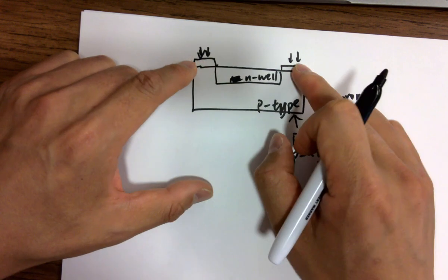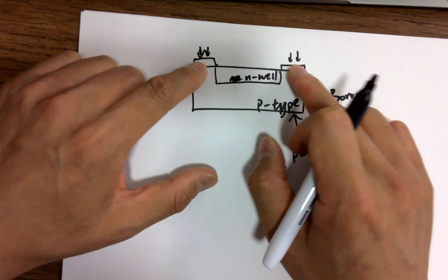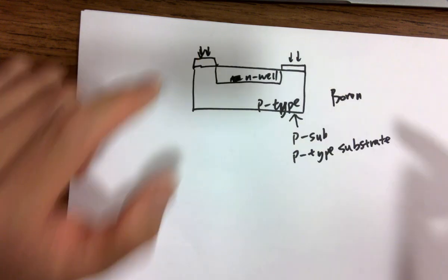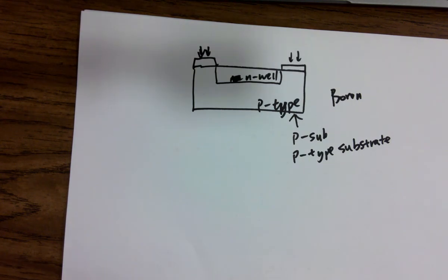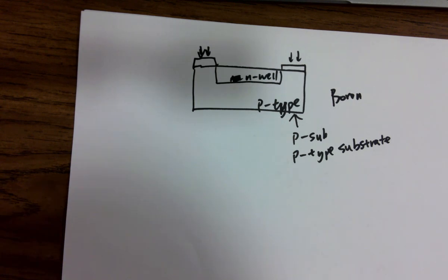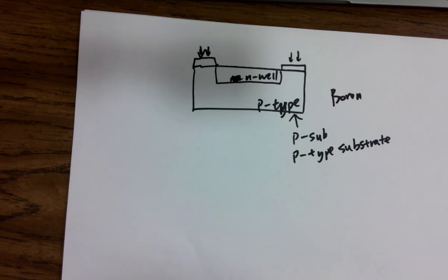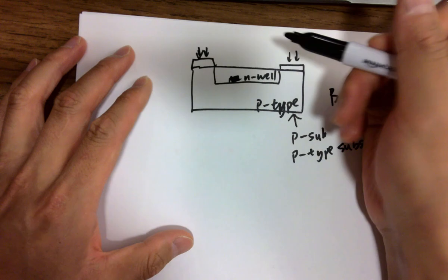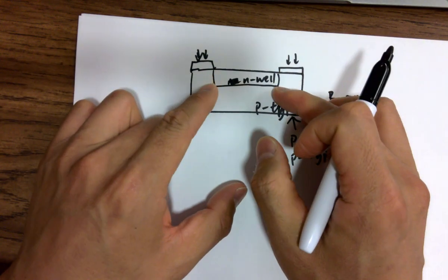That's how that works. And we can use a lot of technologies to block it. It's called photolithography, including the photoresists, including metal pieces, including all the other things. And Gavin did a lot of these microfluidic wafer photolithography. It's very similar to the semiconductor chip design process, even though it's way easier. But it's a similar process. So eventually you can just define a certain type of N-well in there.